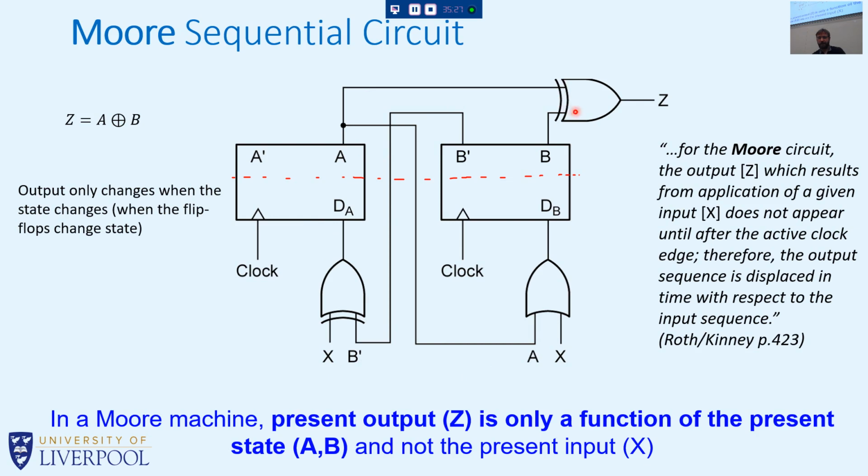And if we know the direction of flow, then we know that this Z must be the output, right? Okay? So that must be the output. And that only leaves us to figure out the difference between X and A and B down at the bottom. Well, clearly, we already know what A and B are. So this is our feedback loop, or our two feedback loops from A and B to affect the next states. This is our next state logic, right? So if A and B are the states of the flip-flops, then X must be the external input. It's just coming from nowhere, isn't it? So this must be the input. We'll just put IP, okay?